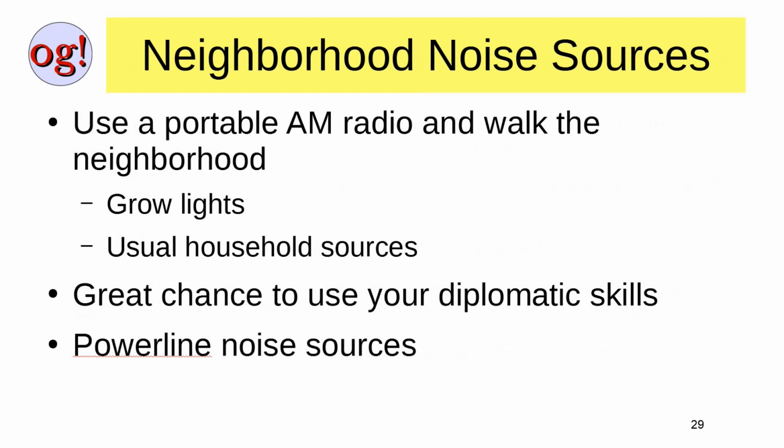Now, I realize that in some areas of the country, people are allowed to grow their own marijuana, and so these are legal installations there. And so this is a great chance to use your diplomatic skills to put some ferrite beads on those grow lights and so on. I mean, technically they're responsible not to radiate, but in practicality, they're just going to thumb their noses at you if you try to force the issue. Okay, and of course look for power line noise sources while you're at it.